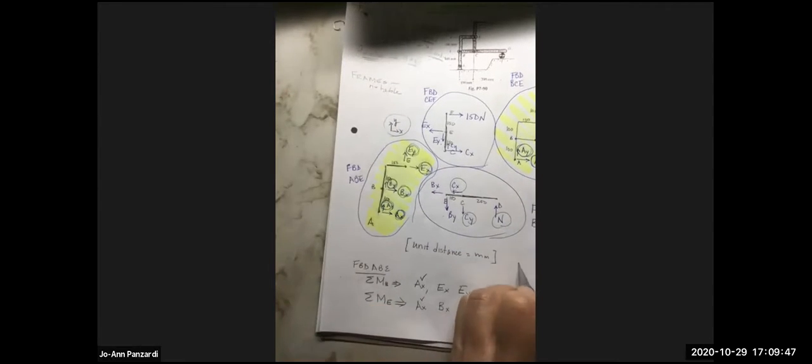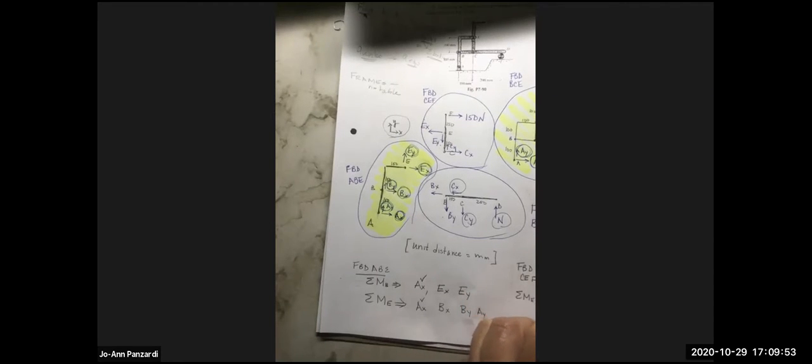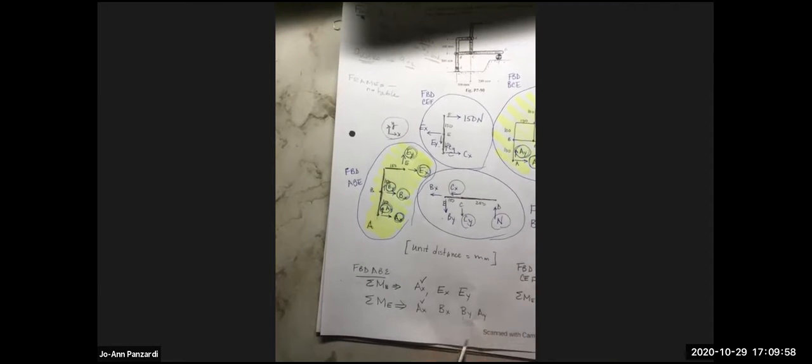So who are we on now, Marcine? Maria, look at one of the other two free body diagrams. Maybe use the free body diagram CEF and do a moment about C. Great. Yeah. So we could use a free body diagram CEF and do the sum of the moments about E, and that's going to have CX in it, and it's going to have 150 in it. We're going to get CX.